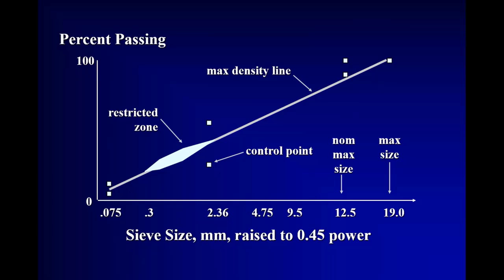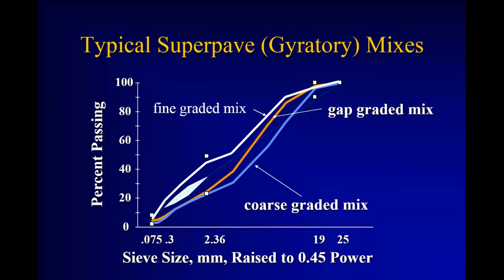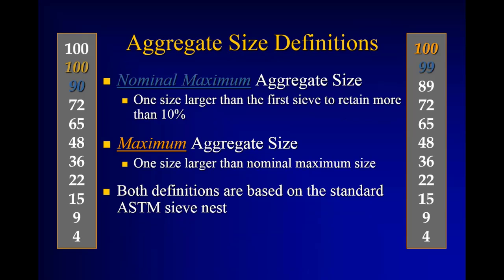That gives us the space to put our asphalt into the mix and to get adequate film thickness of that asphalt on the aggregate, but also sustain or maintain our air voids in that mix. That's the third A of those 3 A's we started with. So depending on the shape and the curvature of this line, we can have coarse graded mixes, fine graded, we can have gap graded mixes like the SMA on 94 west of Jamestown or south of Hankinson to the state line on I-29.